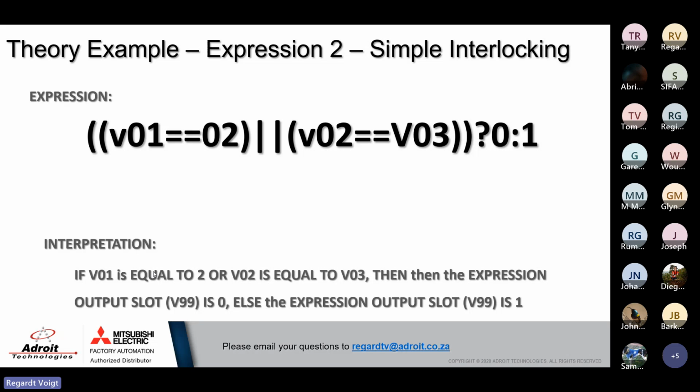Now, as I mentioned earlier, interlocking is recommended for PLC systems, not for HMIs or SCADAs. Interlocking must be done via hardware for obvious reasons, because your SCADA is dependent on the PC, your firmware and software and so on. And if something goes wrong, with the operating system and so on, then the interlocking won't work, obviously.